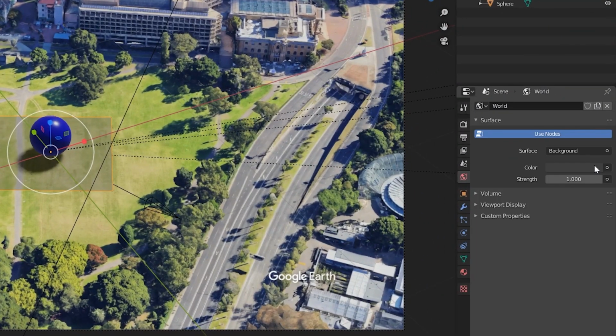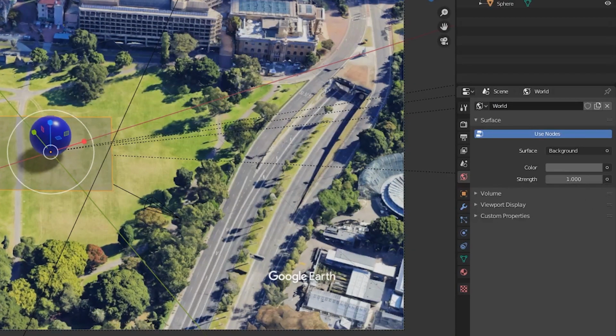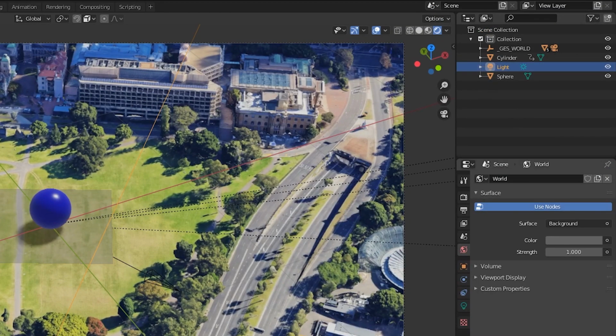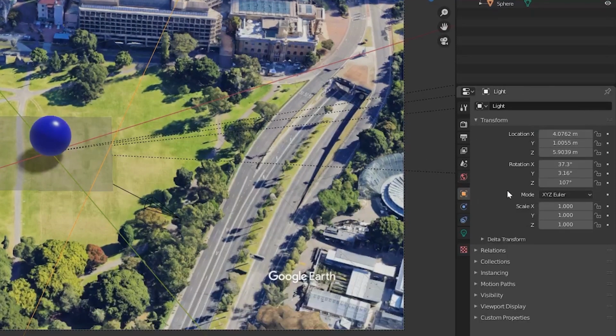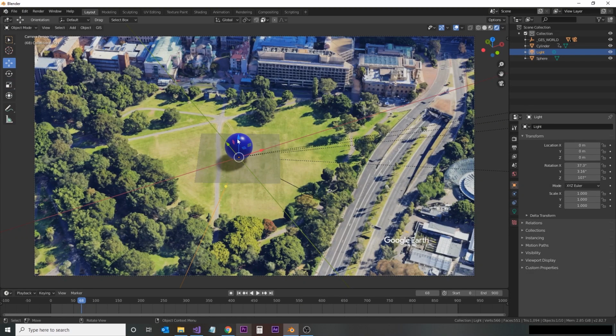As you can see, because of the lighting conditions, the plane itself is slightly discolored compared to the background. So we're just going to set our world color system and then go back into the light and make adjustments so that the colors match. First thing we'll do is put our light in the 0,0,0 coordinate. That just gives us a little bit of an easier chance of aiming the light properly. We'll then use the rotation tool to make adjustments to the angle of the sunlight. And we want to match up the shadow from the trees there as well.